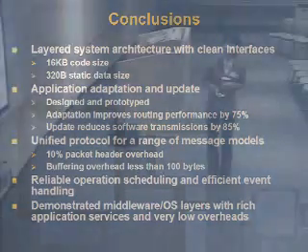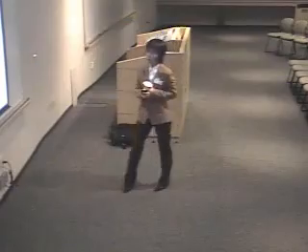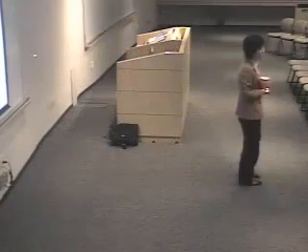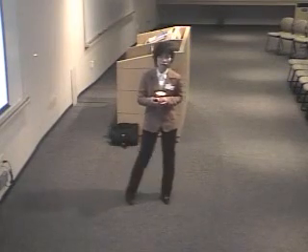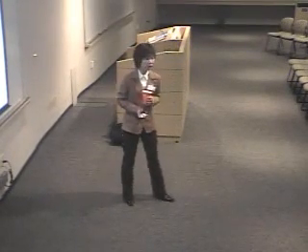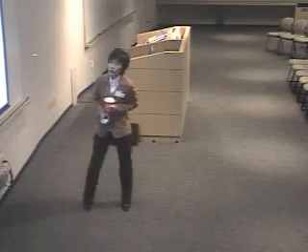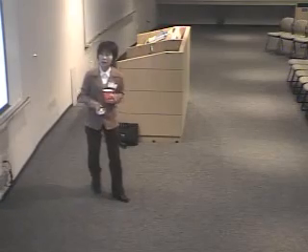To conclude this talk, we have built a layered system architecture with clean interfaces for low-capability and resource-constrained sensor applications. Currently, the system consumes 16 kilobytes of code memory, and its static data consumes 320 bytes. We have designed and prototyped the application adaptation and update. The application can improve routing performance by 70%, and the update can reduce the number of software transmissions by 85%.